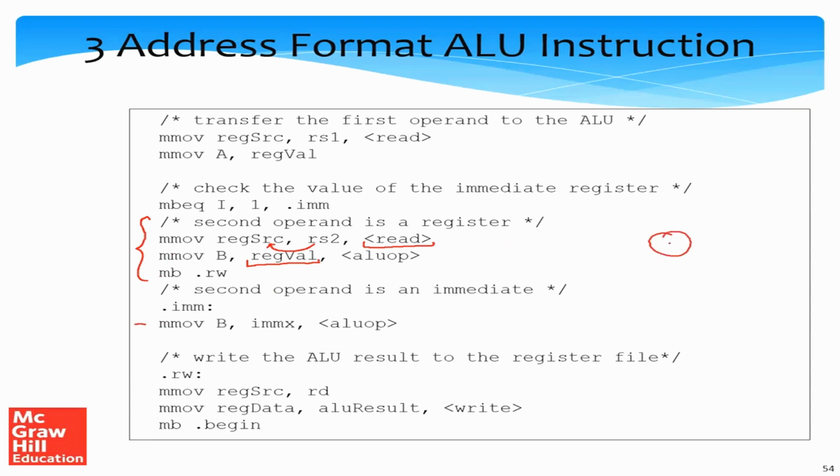Since the value of A is already there and has been set in advance, and now some ALU operation, add, subtract, multiply, whatever, is coming via the bus, and some value is being written to micro register B, we can write it to micro register B and also in parallel send it to the ALU, and the ALU will then process the contents of A and B and the ALU operation and write its result.